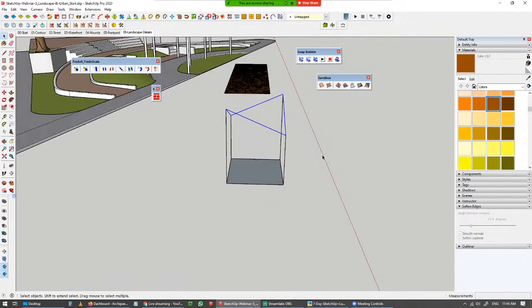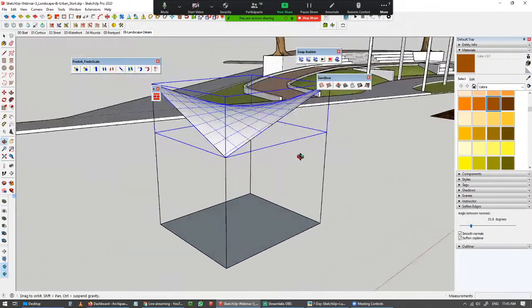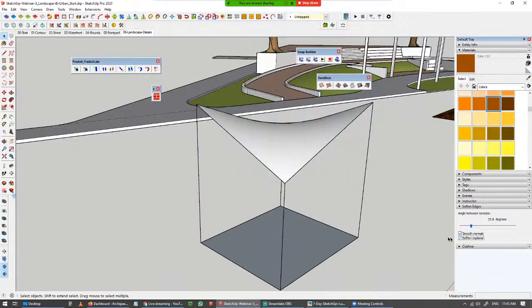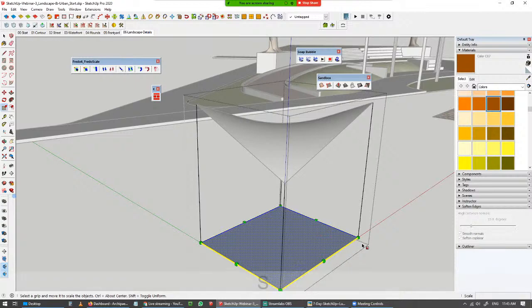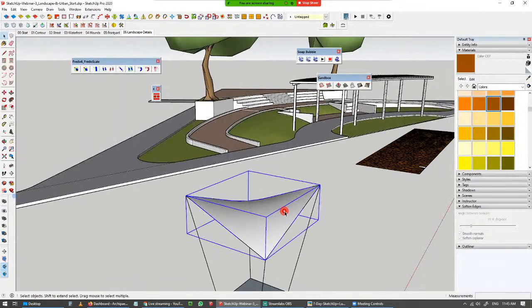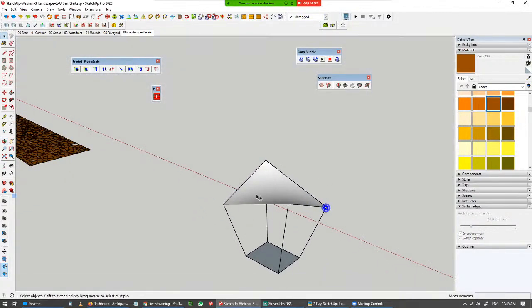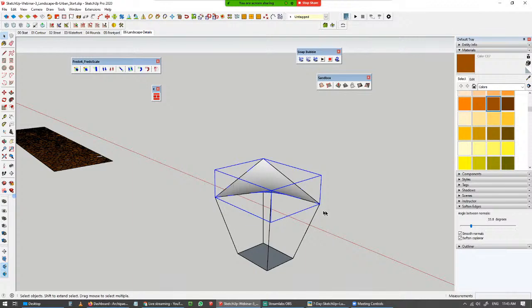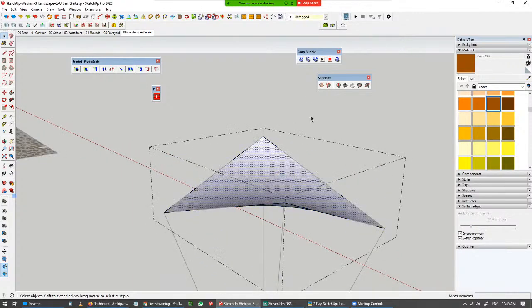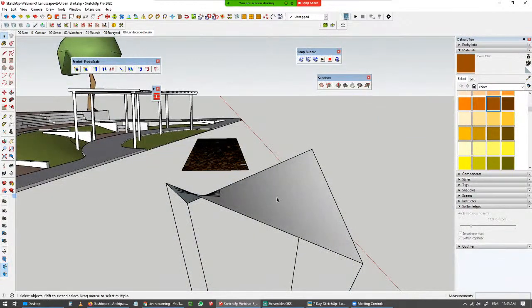This is the profile. I'm going to go with skin. Click here, and divisions, I'm going to go with the default division. Click on enter, and you can see that we have the tensile canopy. Let's soften the edges. Thus we have the tensile canopy in a fraction of a minute. It's not even 1 minute. So you need the outer profile, and all the individual lines will be created by Soap Bubble. We don't need any bubble effect here.